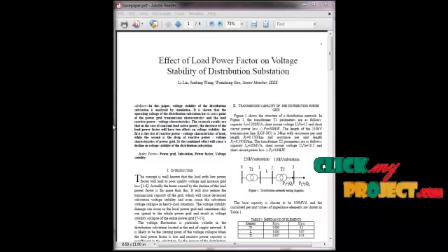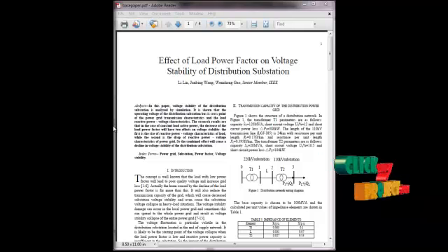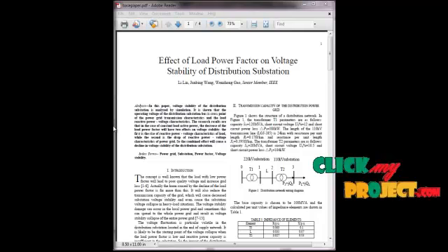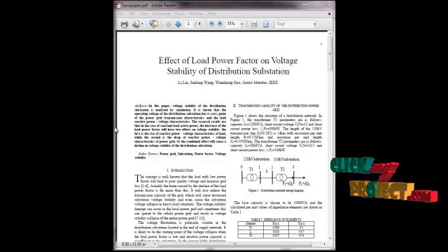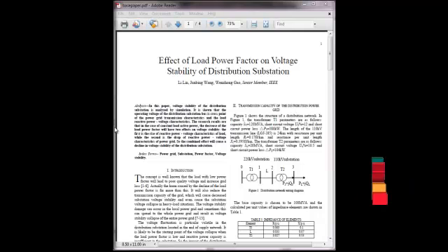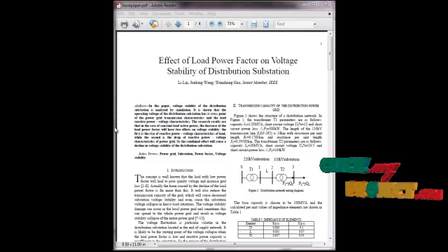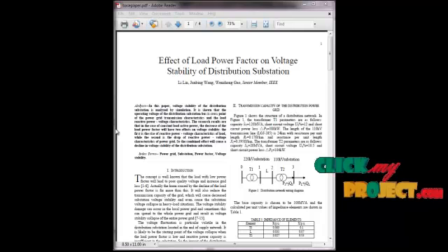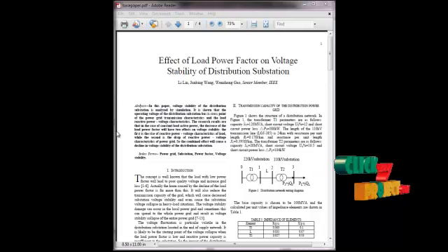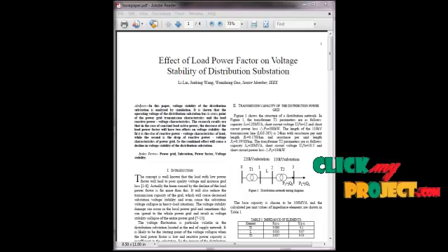Voltage and reactive power control involves proper coordination among the available voltage and reactive power control equipment. Many distribution network operators operate such equipment locally by using conventional controllers to maintain the voltage in the distribution system within the acceptable range with minimum power loss. Different methods have been proposed to improve the voltage and reactive power control in distribution systems, both in planning and in the operation stage. In our paper, we use a DVR to stabilize the voltage in the substation.